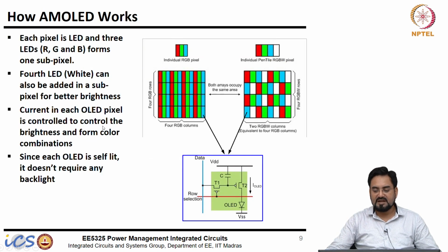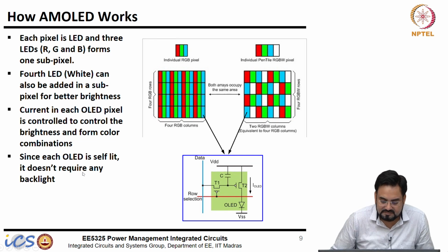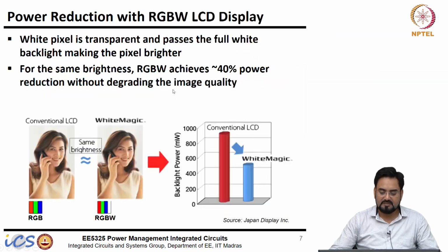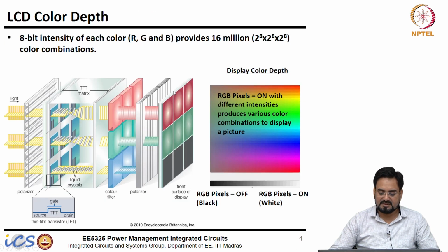So, in case of AMOLED, as I mentioned earlier, since it is LED, it does not require any backlight, and there could be color LEDs, or these LEDs could also be white LEDs, and on top of that you can put a color filter. Just like in this case.